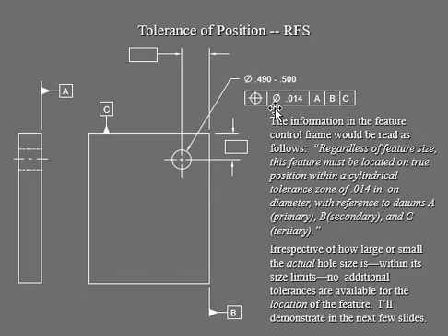That's set here with this little symbol, and we're dealing with the position tolerance. Again, your datum references are A, B, and then C, which are here, here, and here. Don't forget we are in a different view, so some of the surfaces you can see in the front view, but others only in the side view. Since we're dealing with RFS, you don't need the bonus tolerance.